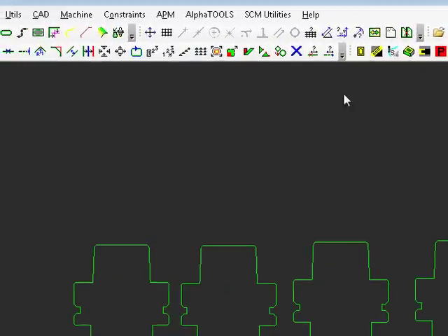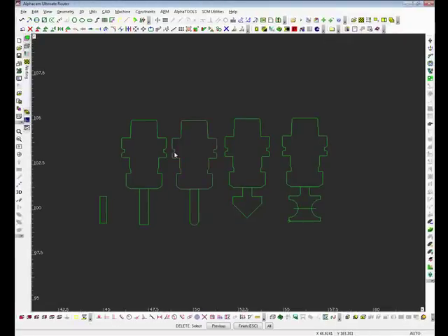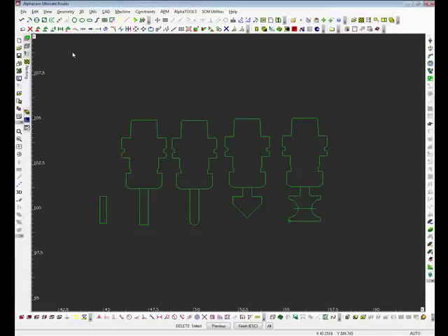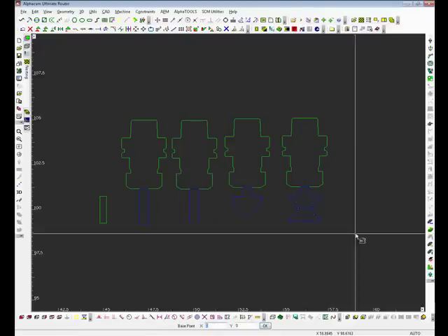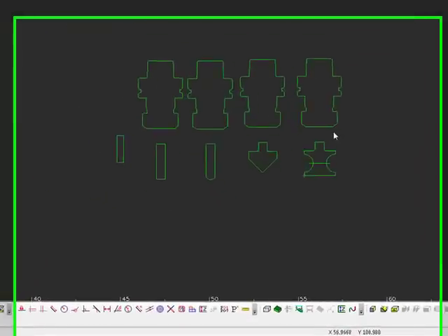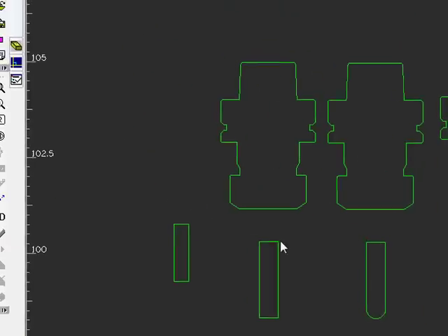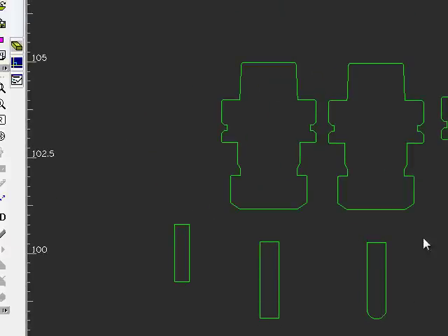holder. What I'm really trying to say is that you will notice the tools are divided into two different categories. They're divided into the physical tool itself and just the holder. It's important to make this distinction because AlphaCam assumes that the geometry of the tool is cutting edge and the geometry of the holder is potential material that will foul your piece.